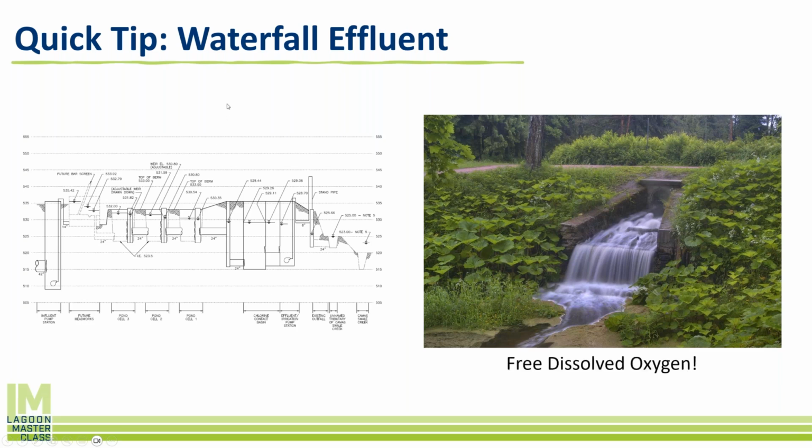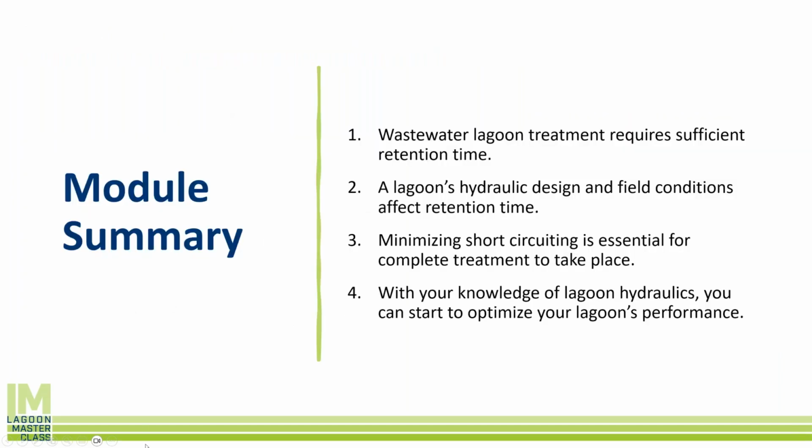So sorry for the rush at the end there. I appreciate your patience. This has been a great webinar. I think the big things that we've talked about here is that lagoon treatment requires HRT. We're holding the water back so the bacteria can do its job. And therefore, how we design the holding back of the water, the hydraulic design of that lagoon system, is absolutely important, especially minimizing short circuiting, just so we're making sure the treatment that we designed to take place does take place. So hopefully with your knowledge of lagoon hydraulics here, you can either optimize your lagoon system's performance, or design eventually a lagoon system that will be installed that will operate the way that you expect.